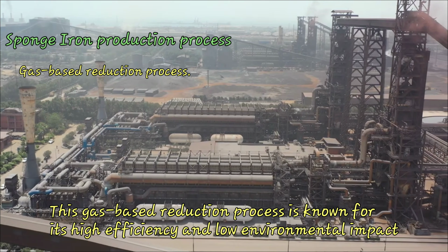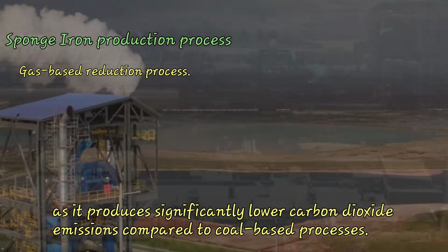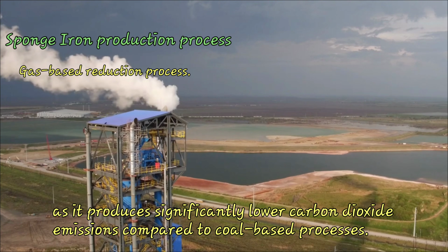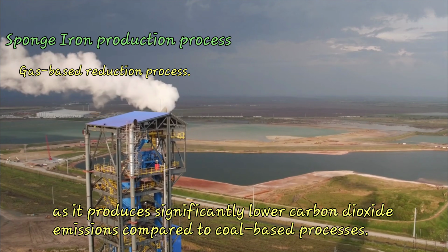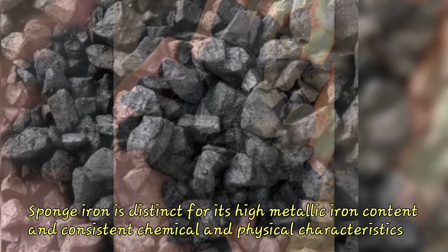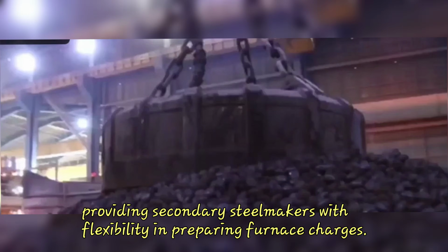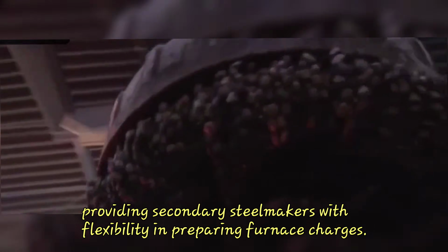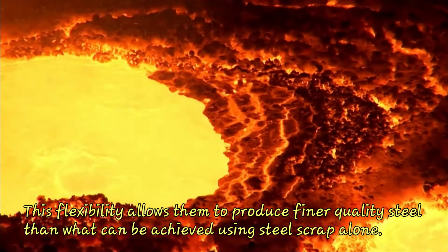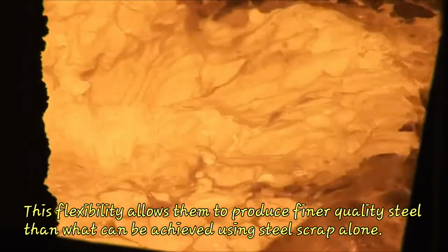This gas-based reduction process is known for its high efficiency and low environmental impact, as it produces significantly lower carbon dioxide emissions compared to coal-based processes. Sponge iron is distinct for its high metallic iron content and consistent chemical and physical characteristics, providing secondary steelmakers with flexibility in preparing furnace charges. This flexibility allows them to produce finer quality steel than what can be achieved using steel scrap alone.